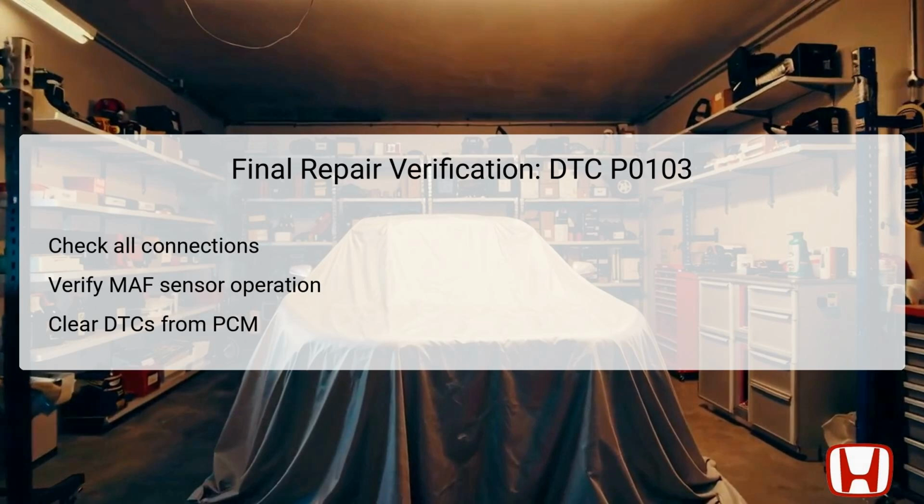After completing the necessary repairs, it's vital to conduct a final repair verification process. Begin by inspecting all connections to ensure that they are secure and free from any corrosion or damage. After confirming that everything is connected properly, verify that the new or repaired MAF sensor operates within the specified parameters.